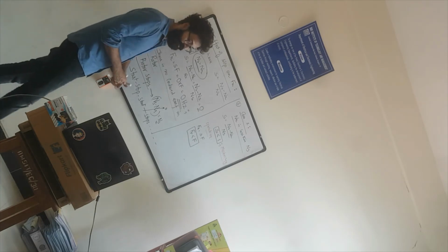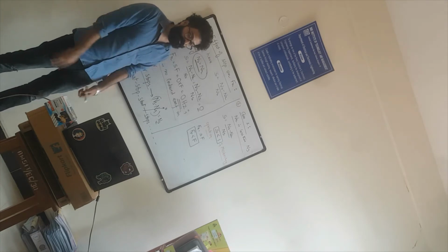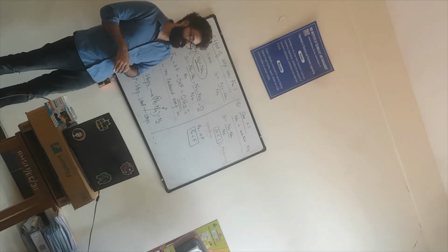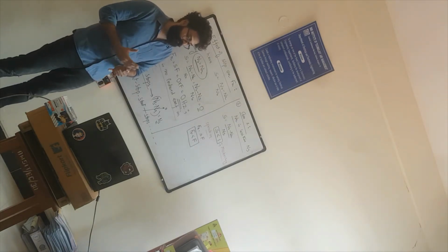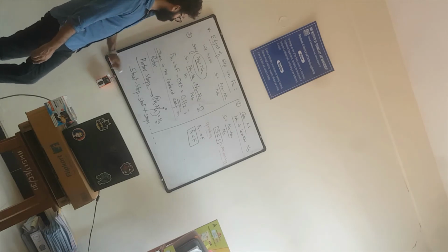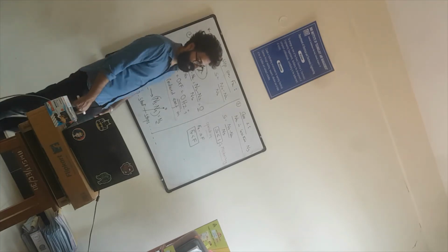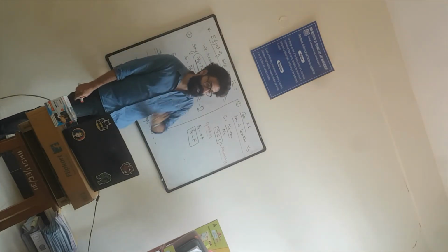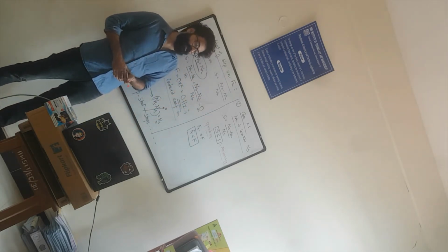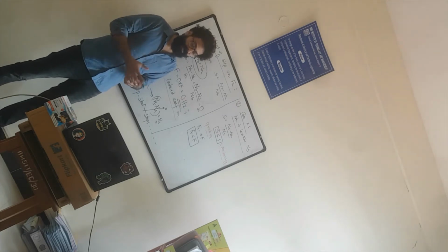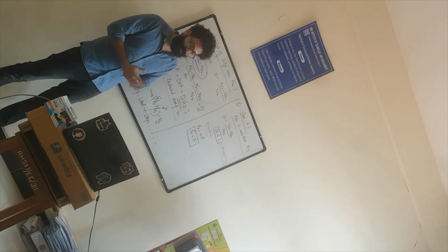Which is highly objectionable, right? Because we don't want our ceiling fan to get into this start-stop situation. Because if it gets into a start-stop situation, what happens? You will not get any useful operation from it, right? So this condition needs to be avoided. But will it happen in a physical machine? No, it won't happen in a physical machine. That's because your rotor will have a certain moment of inertia, right? Because the rotor consists of windings, and once again your rotor is fitted with a shaft, etc., etc.